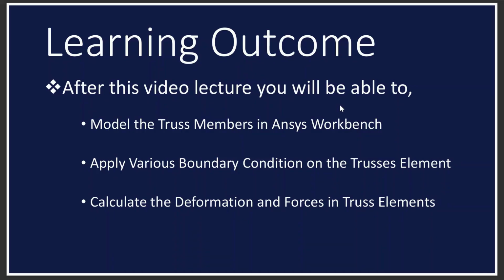After completing this video tutorial, you will be able to model the truss members in ANSYS Workbench. Then you can apply various boundary conditions on the truss elements and calculate the deformation, reaction forces and axial forces in the truss elements.